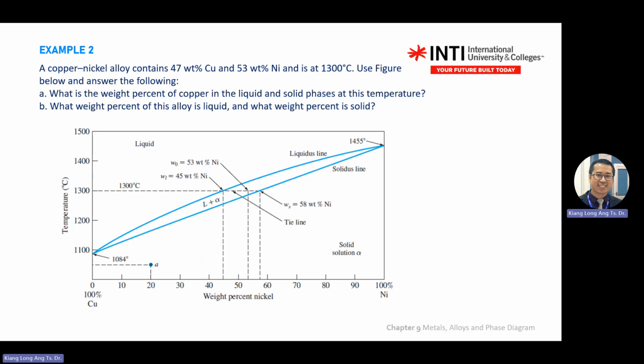At one temperature, 1300 degrees C, go to the graph, find 1300 degrees C, and draw a horizontal line across the whole graph. You will get intersections, three points, because you already drew the X line. So you draw the 1300 line and you will see three points. Without looking further, you already drew X and the temperature. Next, you are drawing the tie line.